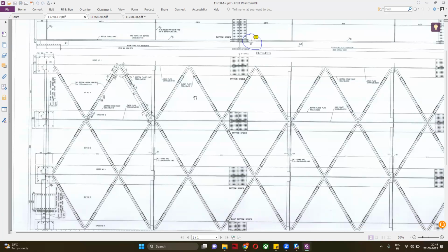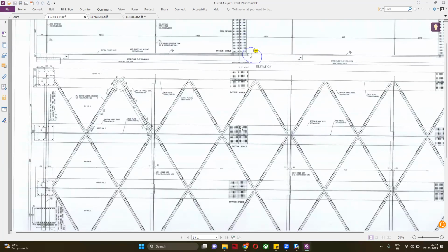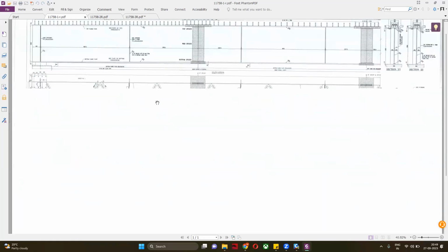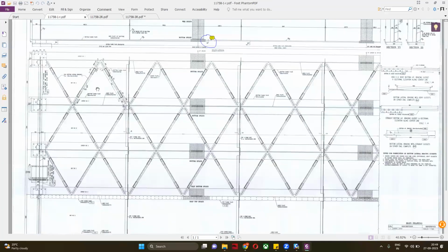That's why I'm using it. You can follow it anywhere you require this steel drawing for your project. It is valid for 36 meter. You can adjust it for 32 to 40 meter a little bit by changing the web or flange thicknesses.